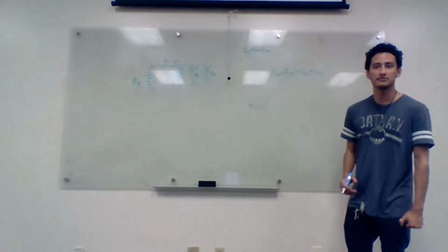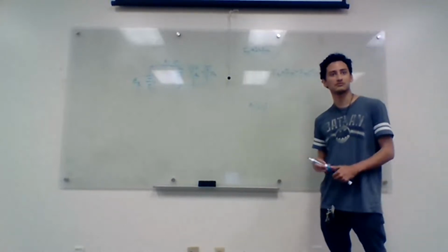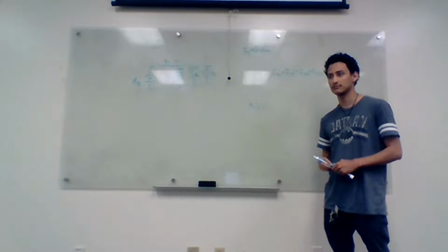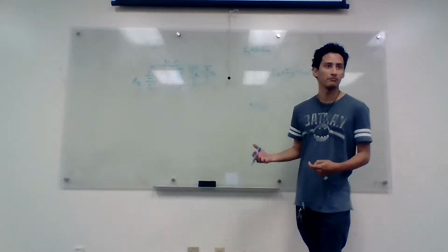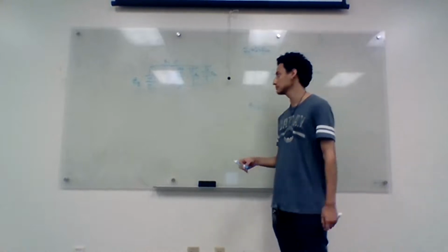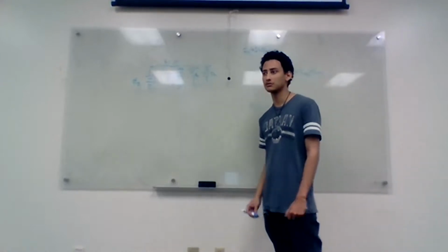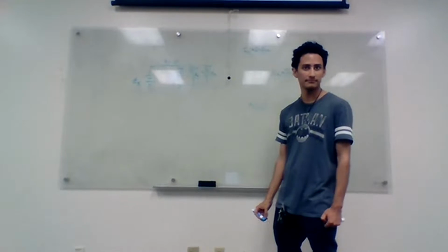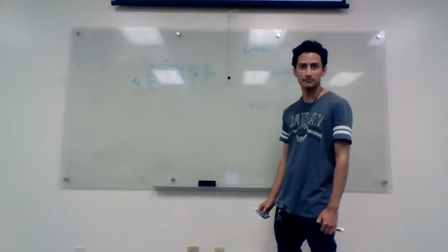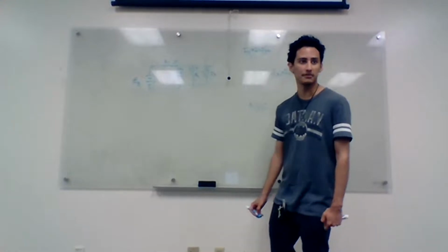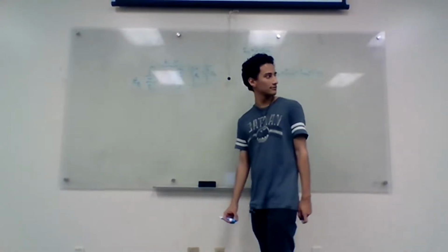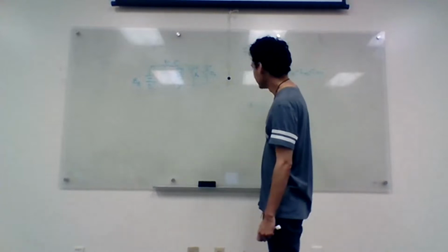With some quick things that you can say about the voltages that are pretty important. Circuit wise, what voltages are the same? And what should the KVL add up to? The diode voltages and the resistor in the middle are voltages in parallel, so they're going to be the same, the same drop across all of them.